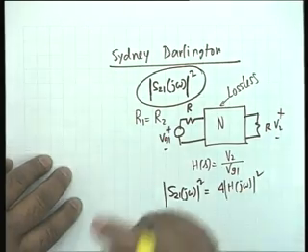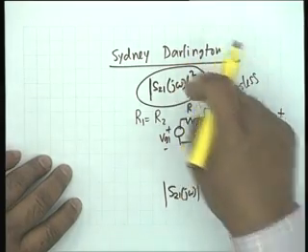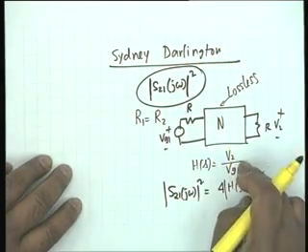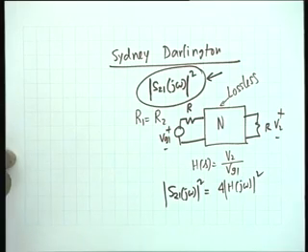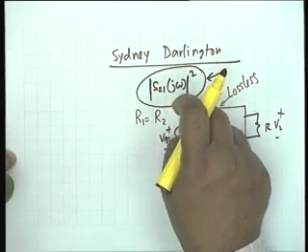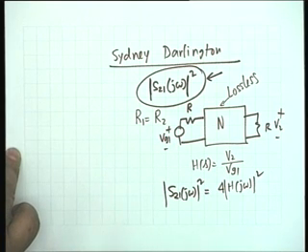So, if this is given, S21 j omega squared, or the voltage transfer function is given, or something else, if the insertion power ratio is given, then you know insertion power ratio and S21 j omega squared are reciprocals of each other, and therefore in any of these circumstances you can find out what S21 j omega magnitude squared is, and from this Sidney Darlington was able to synthesize the network, and the steps are like this.